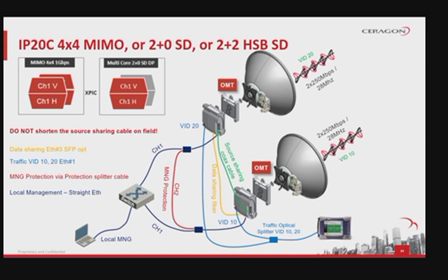B. For 2+0 space diversity, only one of the network elements on one side will have radio transmission. The other network element in the site will be connected to a second antenna, but completely muted, only with reception.